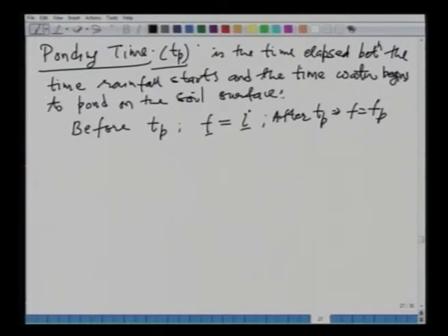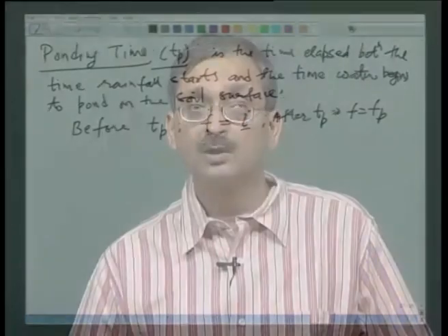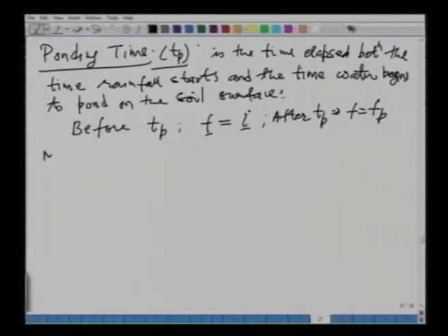Okay. So, calculation of this ponding time is an extremely complex process. There are various researchers who have worked on this and tried to give expressions. What we will do in this course is we will look at one method which is proposed by Mein and Larson, and it uses the Green-Ampt equation. The advantage of this is that the Green-Ampt equation is an exact analytical solution of a simplified version of the schematic. So, let us look at Mein and Larson's procedure, which was given in 1973.